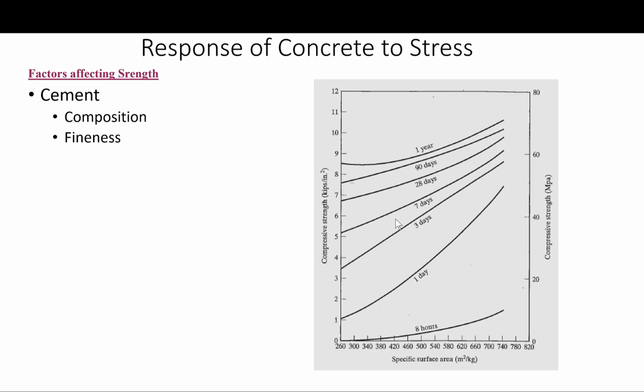So the relative strengths obtained with the 5 standard types of Portland cements were shown previously, if you refer back to those lectures. And although there were considerable differences in strength development up to 1 month, at later ages, as I just said, the differences among the 5 standard types of cements become less important. So cements that hydrate more slowly, whether through changes in the composition, curing conditions, or the use of admixtures, tend to develop higher ultimate strengths.